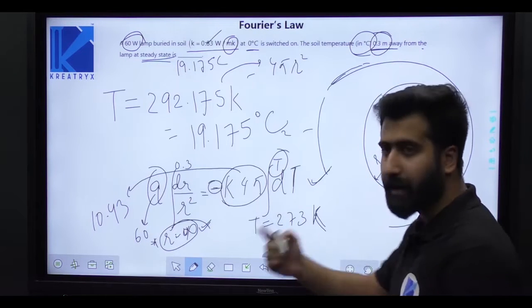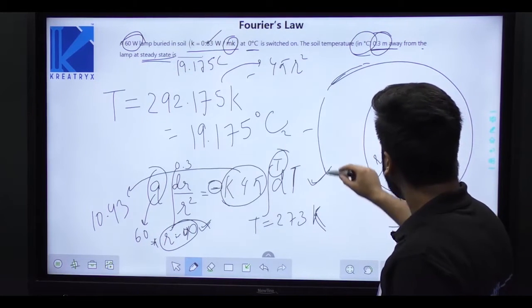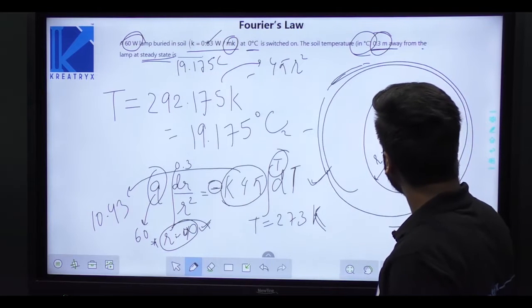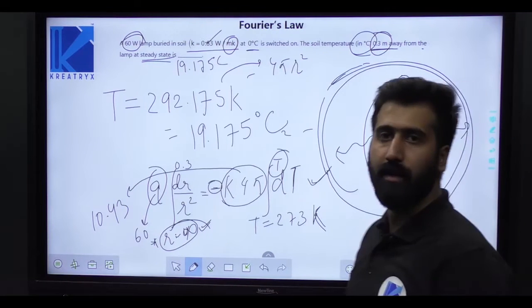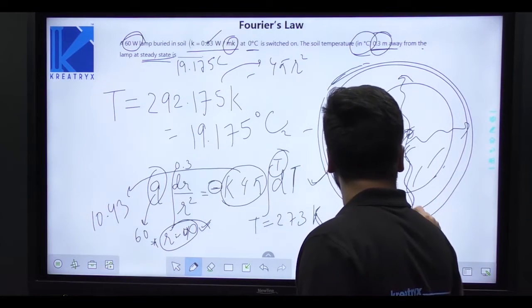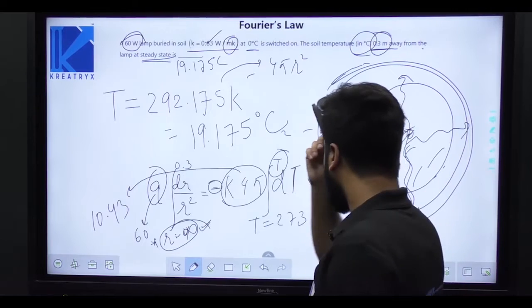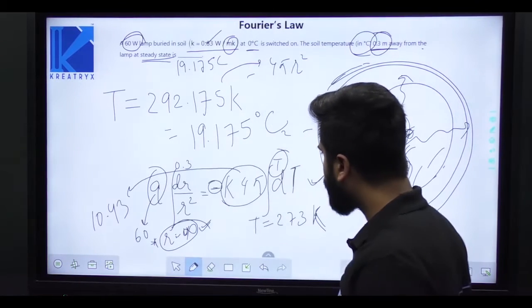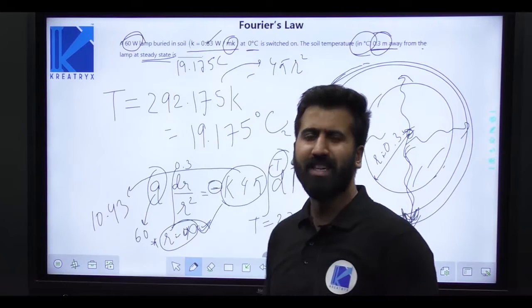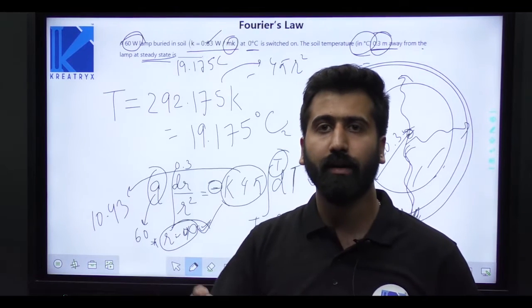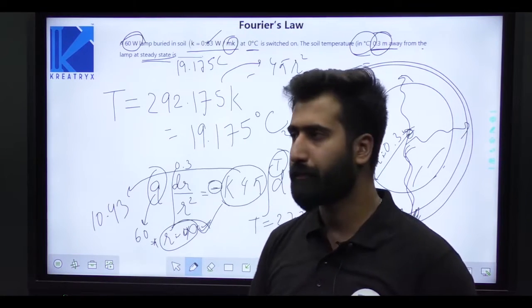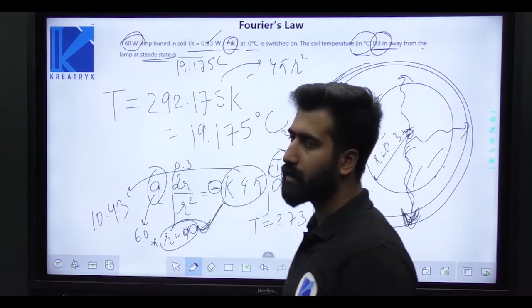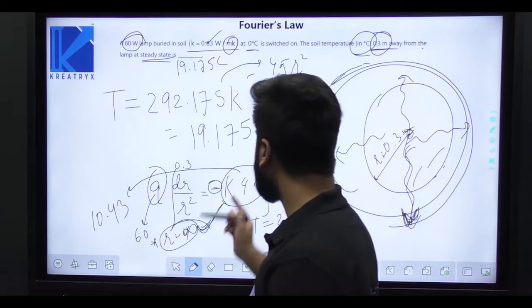This was actually a nice question, because first of all you would feel difficulty in writing the area. You will have to understand that the heat will be conducted radially in the form of a spherical area. And the next part was taking the limits, because at R is equal to 0 you do not know the temperature, but at a very far away distance from the lamp the temperature is still 0 degrees Celsius. So you can directly use that limit. It was a nice question.